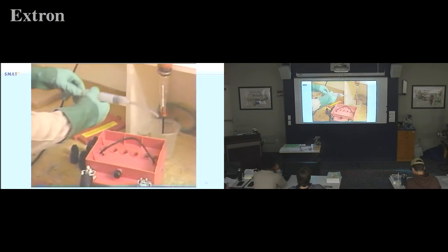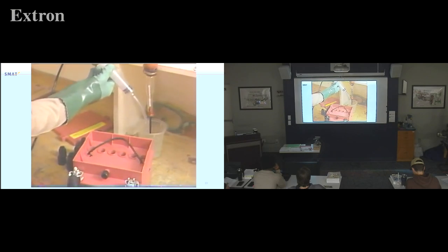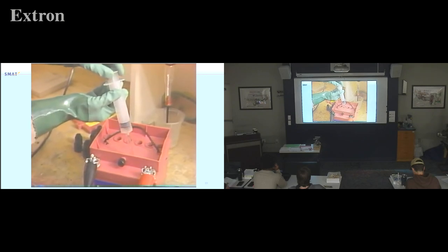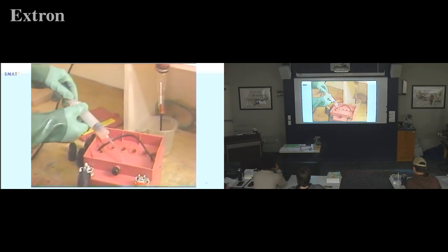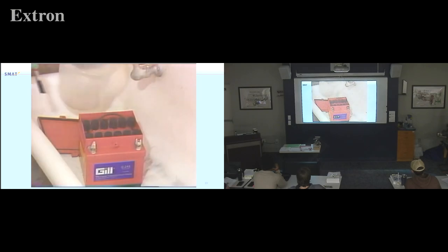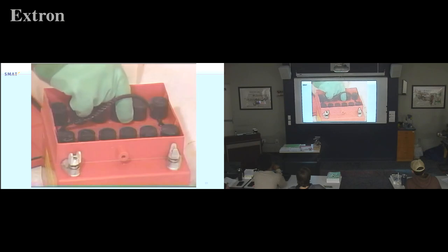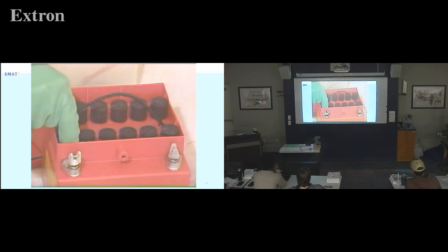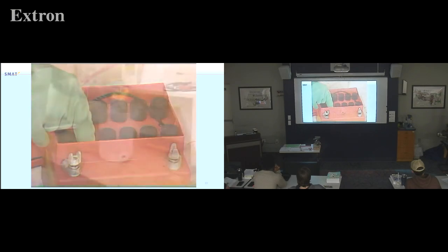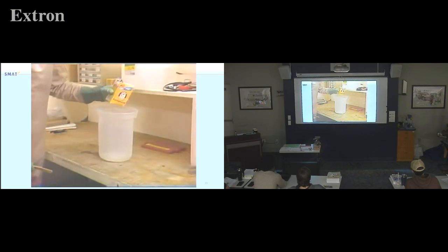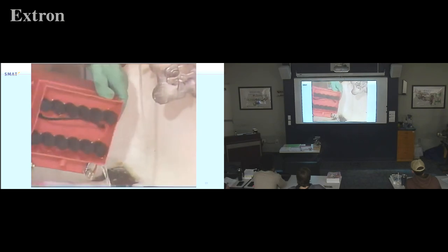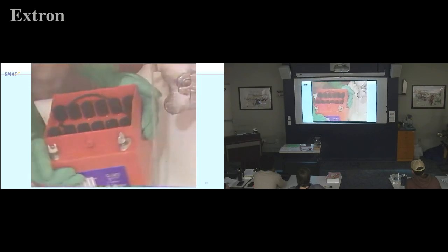Before disconnecting the fully charged battery from the charger, again check electrolyte levels and add or remove electrolyte, if necessary, to maintain the level just at the bottom of the split rings. After you remove the battery from the charger, neutralize any spillage on the top of the battery. Be sure that vent caps are on tight, because just a small quantity of baking soda in a cell will significantly reduce its power. Ordinary baking soda and water is the best neutralizer. Wash the battery top thoroughly with clean water and dry the entire battery before installing it or putting it away.